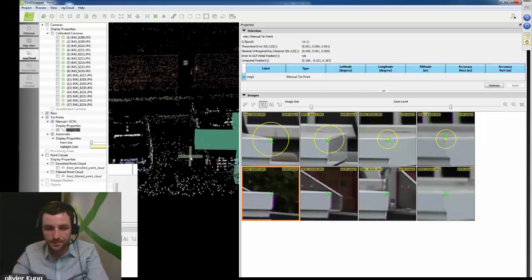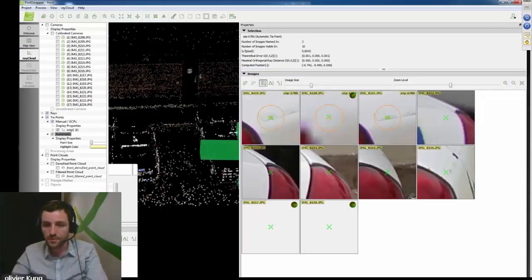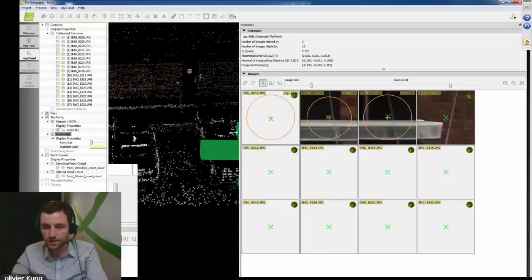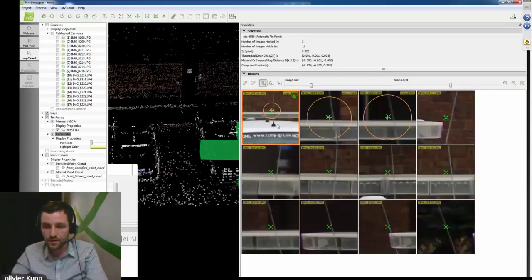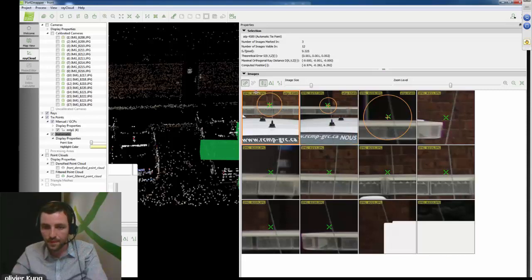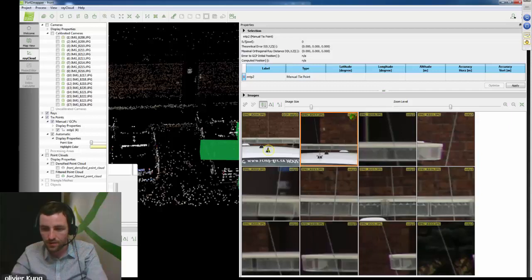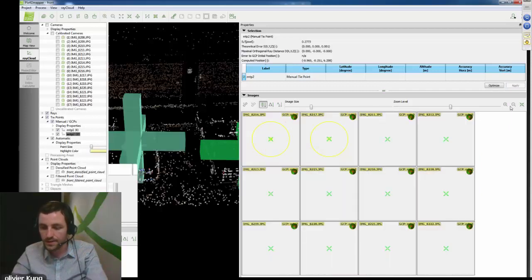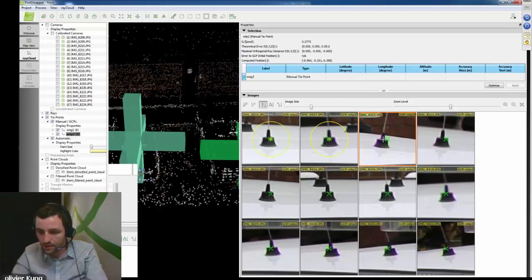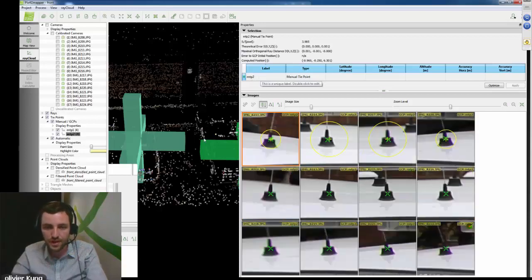I will then repeat the same step for a minimum of 3 manual tie points. So we can do it from the other part of the car. Let's say that we do it from the antenna. That sounds something that can be easily spotted from the top. So again, I create a manual tie point. I click once, twice at least. I check. All right, I can improve a bit by clicking here and here. Apply, done. That's my manual tie point called MTP2.